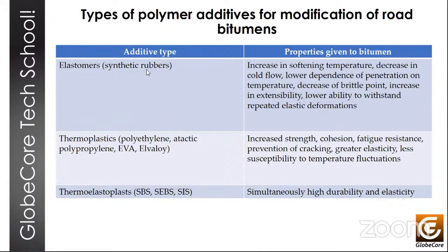Today, polymers are most often used as modified additives for road bitumen. So practically every known polymer out there has been tested in bitumen polymer compositions, while the range of the polymers that are actually used in practice is rather narrow. A necessary condition for obtaining a polymer bitumen binder is the compatibility of both components, meaning the ability of a polymer to dissolve or swell in a bitumen dispersion medium.